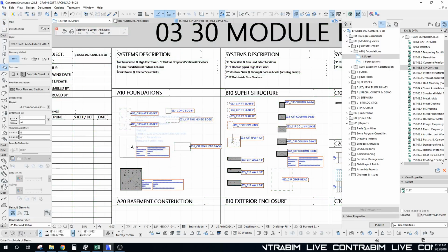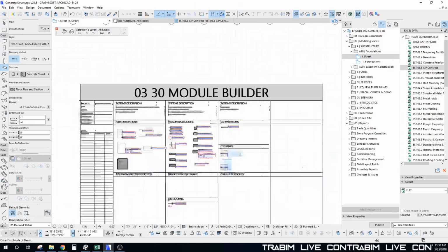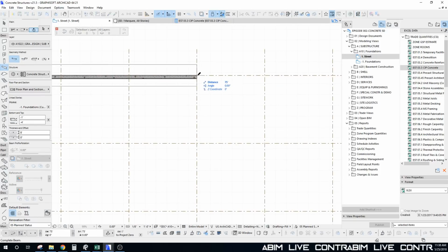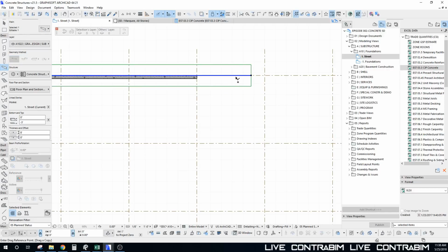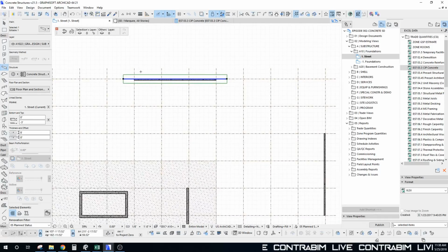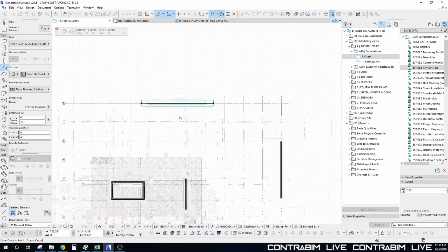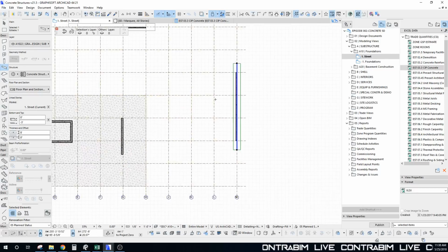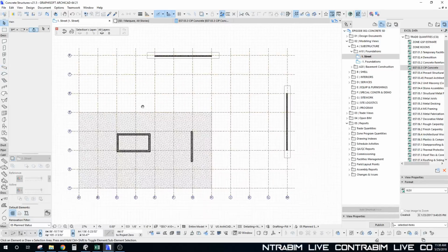Okay, so let's go ahead and pick up our grade beam. We're going to add our grade beams and extend this a little bit past it. If it's 75 feet, looks like I'm doing 95 feet, and we'll have a 10-foot overhang on each side. Probably more than what we actually need, but oh well. Take that and just copy and rotate it around, and there we got some beams.